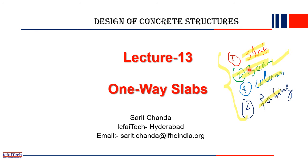If you understand each element of a structure individually, then if you combine all, you will get the entire structure. Similarly for a bridge, the loads are transferred on the bridge deck, which is nothing but a slab, and this deck rests on a beam, and through the beam the load goes to the bridge pier, and ultimately through the foundation the load is transferred to the soil. That is a typical load path of any structure. Now in this lecture we'll be discussing slab design.